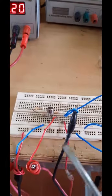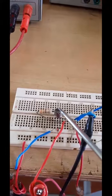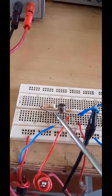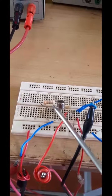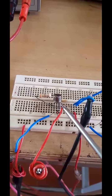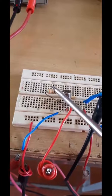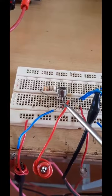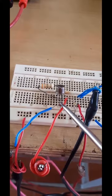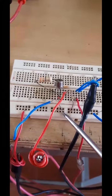Now let us wire up the circuit. SL100 is connected here, and a resistor of value 330 ohm is connected between the collector and base of this transistor. This is the emitter, base and collector. The negative side of the zener diode is connected to the base of this SL100, and the other point is grounded.